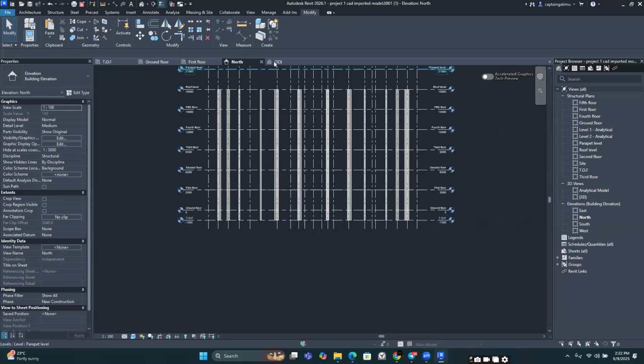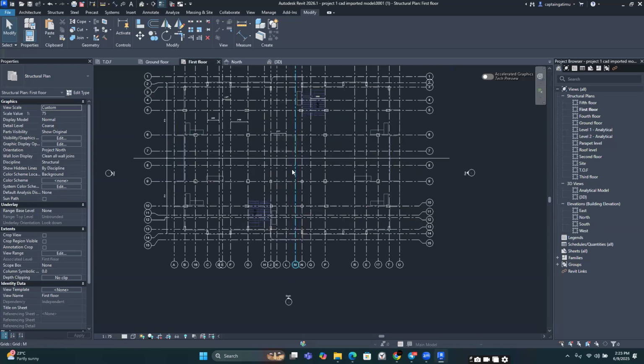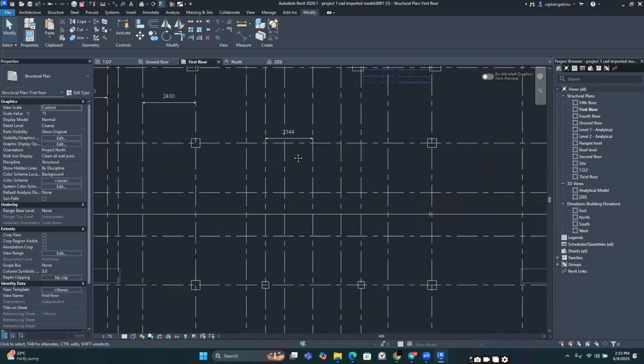All right, so I hope you are together up to that point. So I'll proceed to model the shear walls at this point, since it's also really easy and it follows the same workflow. All right. To model the shear walls, we are going to do it in the first floor where we have our CAD file, and then we are going to copy them to the other floors as we did for the other elements.